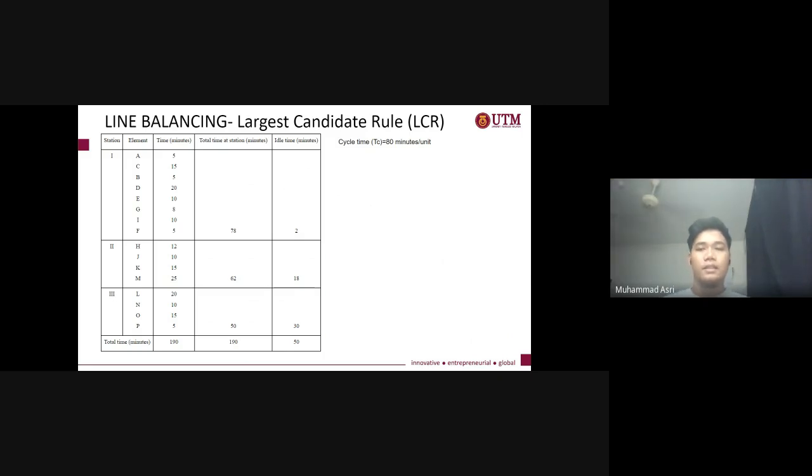First station: A, B, C, D, E, G, I, and F. The total time in station 1 is 78 minutes, and the idle time is 2 minutes. For station number 2, we have H, J, K, and M. The total time at station 2 is 62 minutes, and the idle time is 18 minutes.